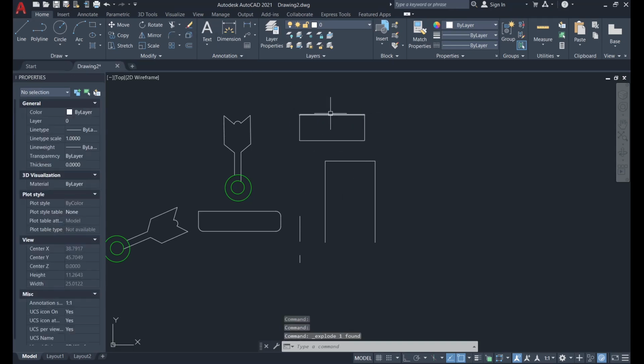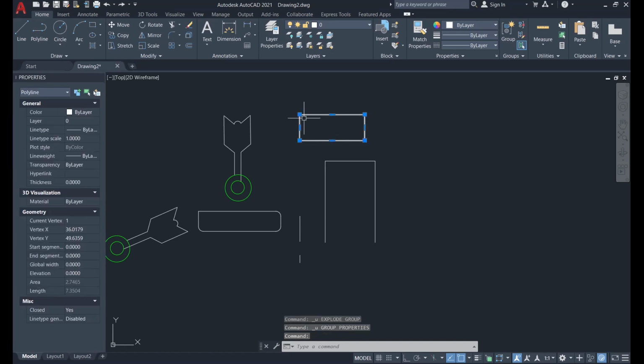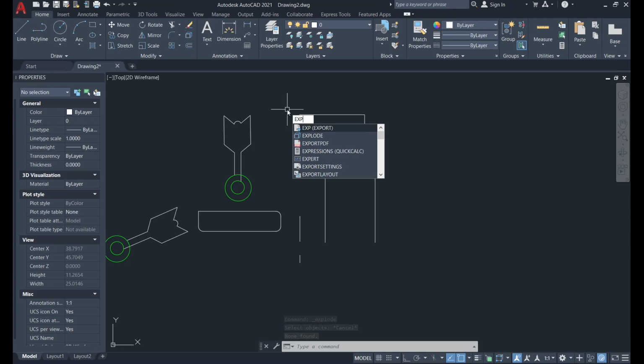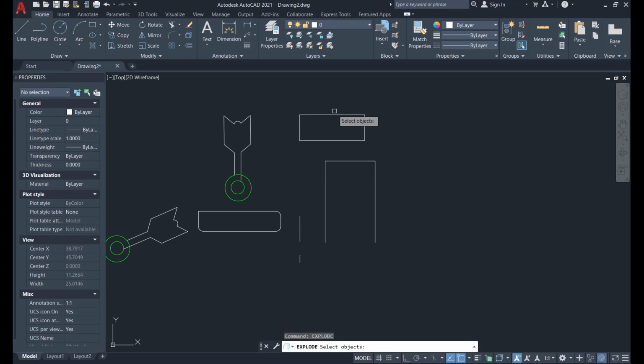And if I use the explode, I have already used it because my shape was selected, so I undo that. Okay, now it's back to a full rectangle. I access the explode or just write on screen the shortcut, X, and this is the shortcut when you go to the second command from the list. You're going to explode.